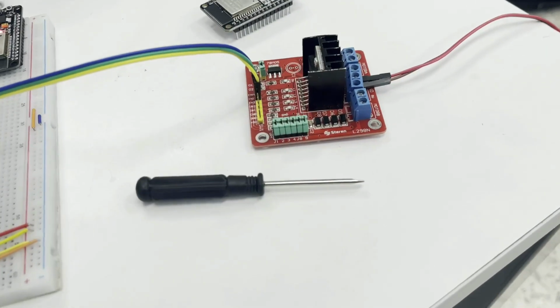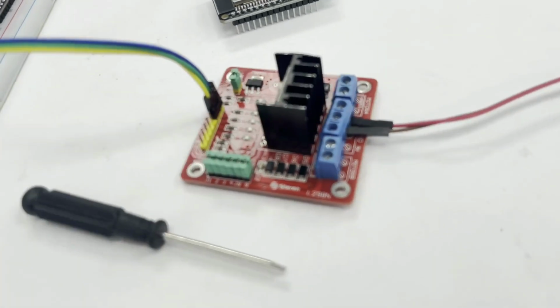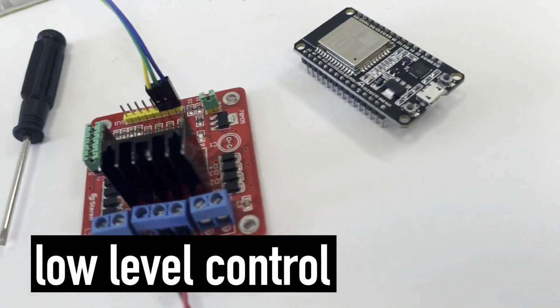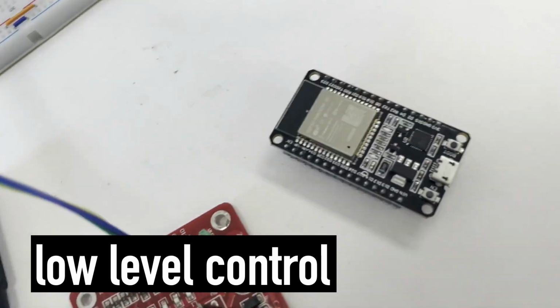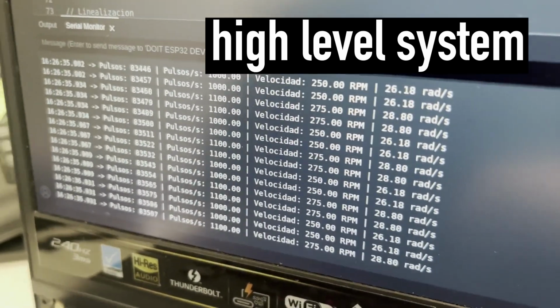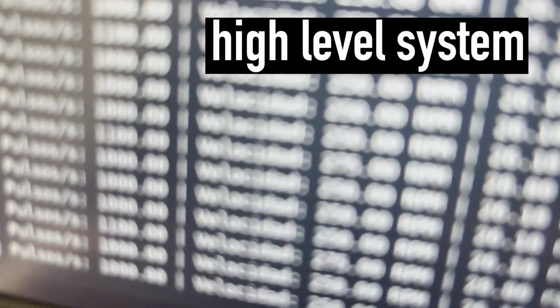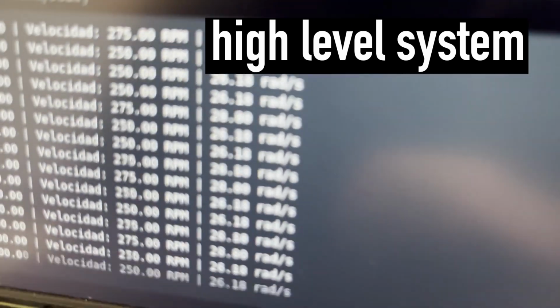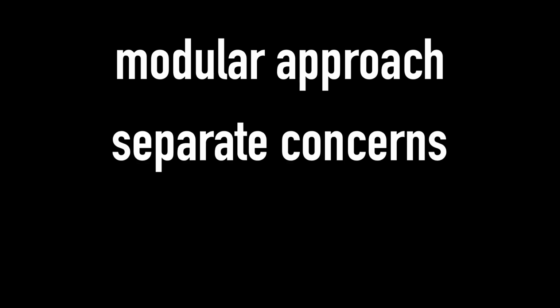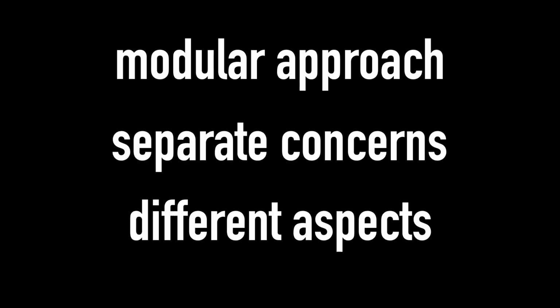To achieve this, we follow a structured approach. The ESP32 microcontroller was responsible for low-level motor control, receiving commands from the ROS2 system using micro-ROS. Meanwhile, the high-level system took care of setting target velocities, monitoring real-time performance, and ensuring everything worked as expected. This modular approach allowed us to separate concerns effectively and focus on different aspects of the project without overlap.